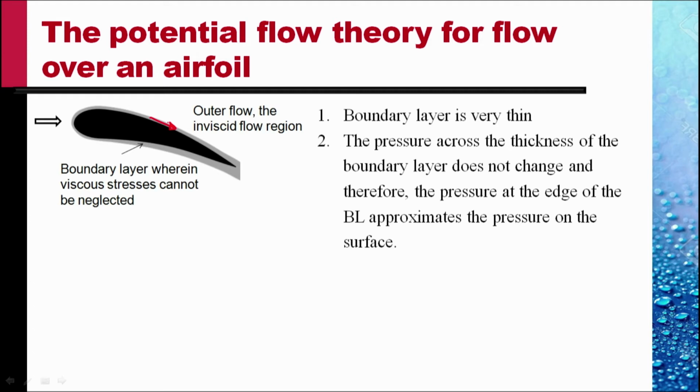But the boundary layer is very thin, and if it is thin, to the first order approximation, we can neglect this altogether, so that we can treat the outer flow as, to first approximation, extending right up to the surface of the aerofoil, provided the boundary layer is thin, that is, the flow does not separate. That is, for low angles of attack on a rounded nosed aerofoil.